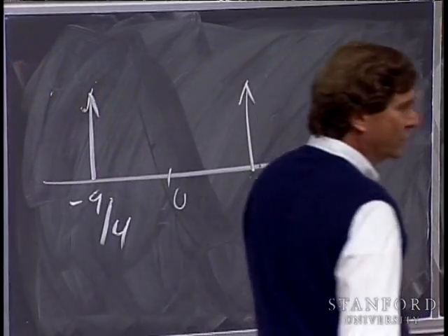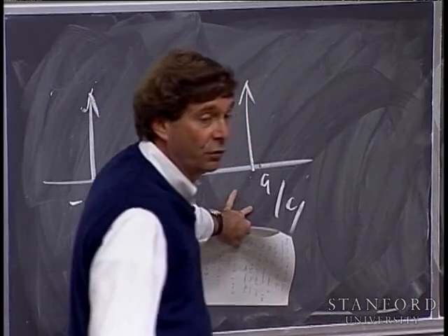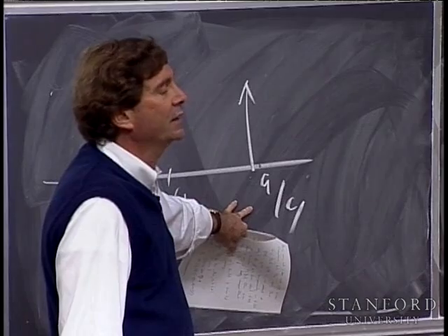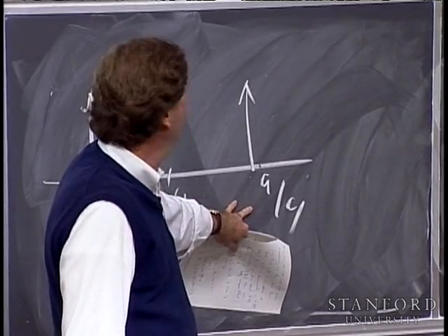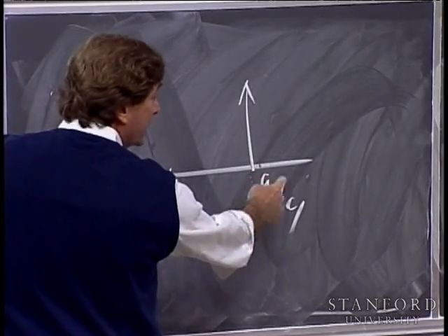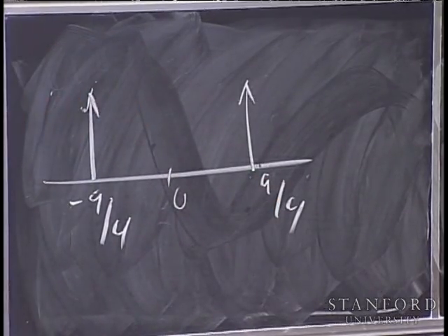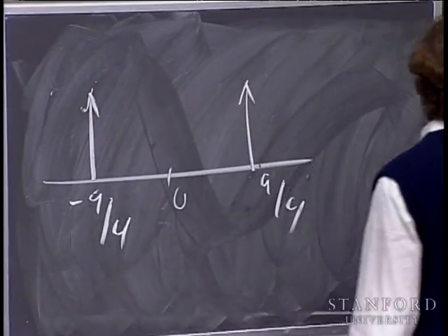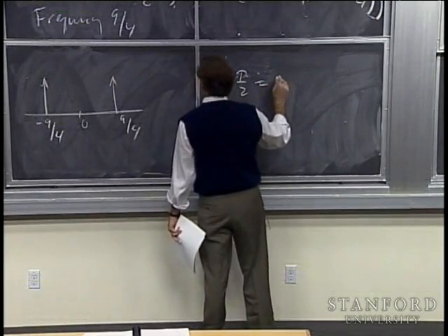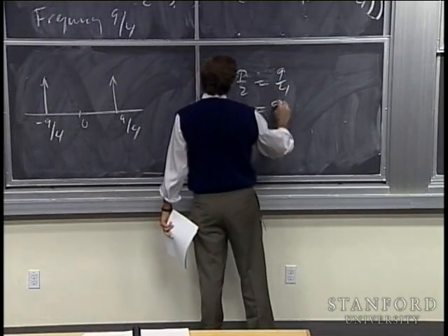So the proper sampling rate would be anything greater than actually 9/2, twice this, because the whole bandwidth would be okay. You would want to convolve with a Shah function of spacing p. Here p over 2 is 9/4, so p is equal to 9/2.